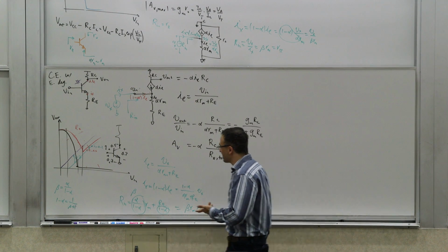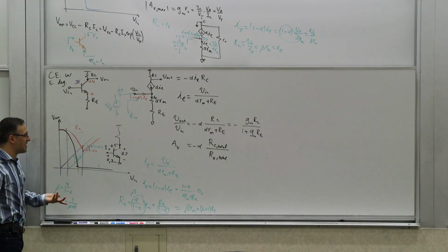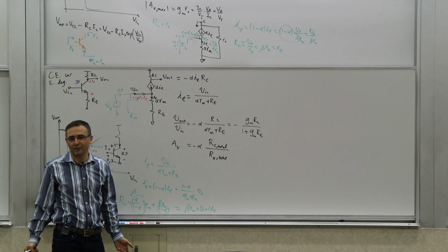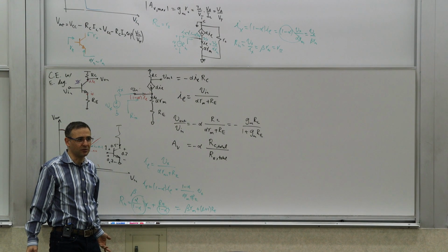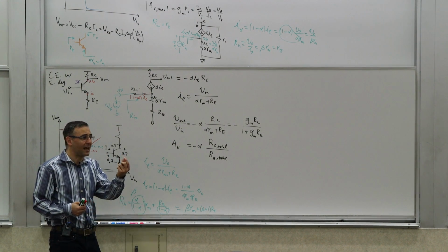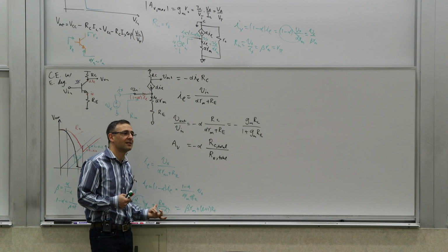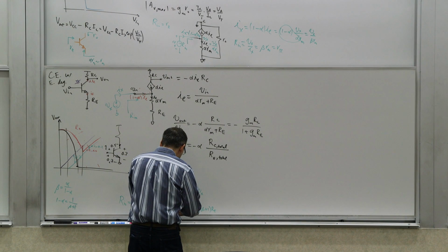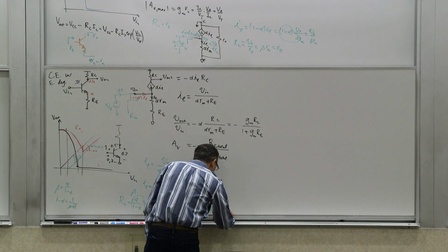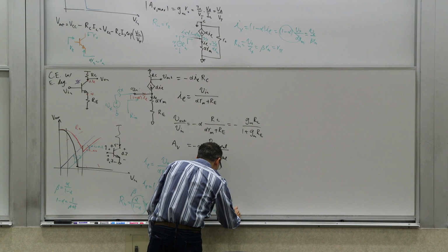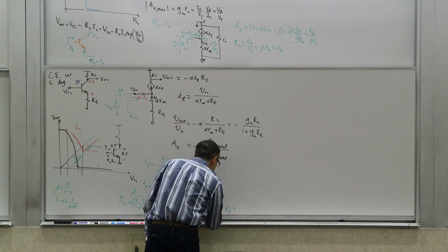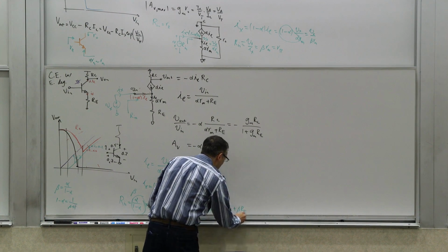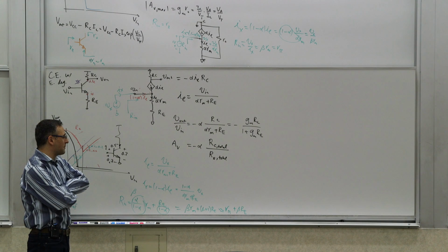Right? So I wouldn't get too hung up on this beta plus 1 a lot of times. It shouldn't bother you. If it makes your life easier to make calculations, that's the assumption that you need to make, because it's built upon layers of assumptions already anyway. But what is beta Rm? Let's write this thing. Beta Rm is R pi. So it's R pi plus, roughly, R pi times beta Re. If I want to remember it one way, this is probably not a bad way to remember it.